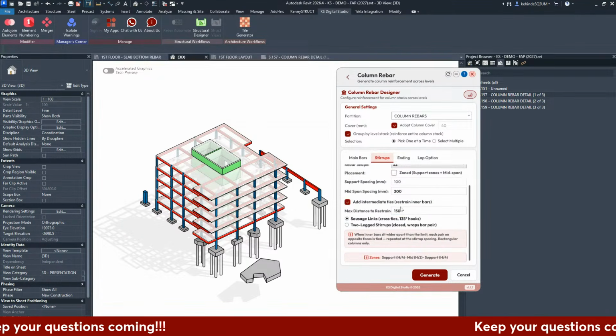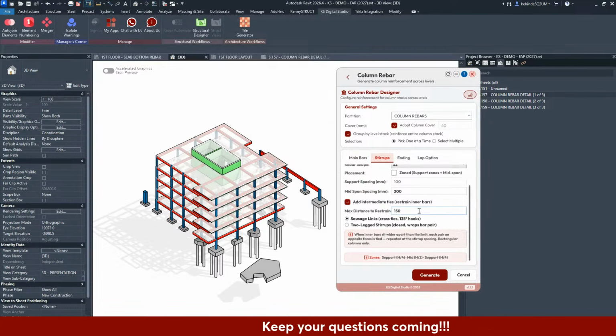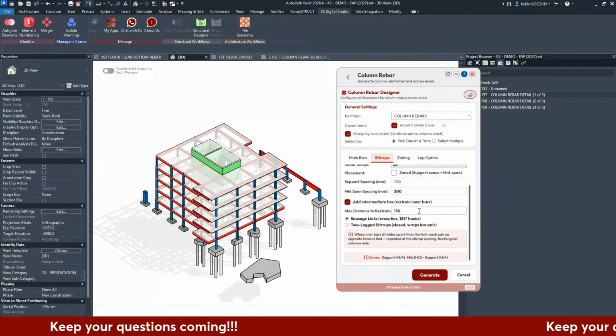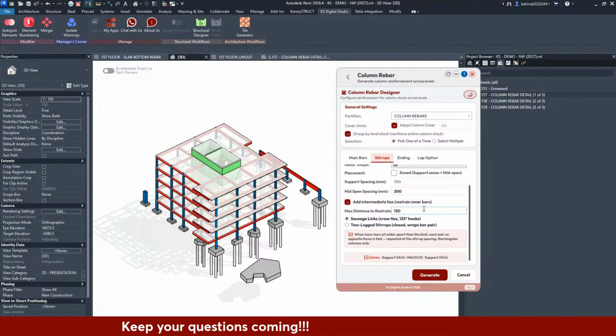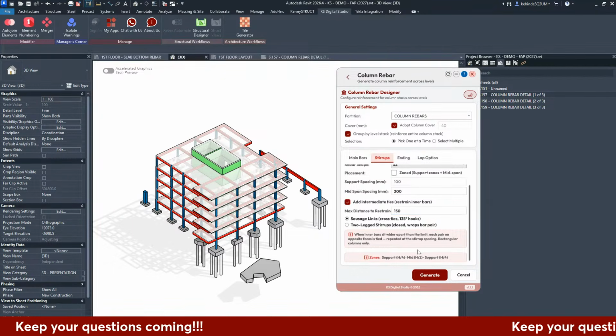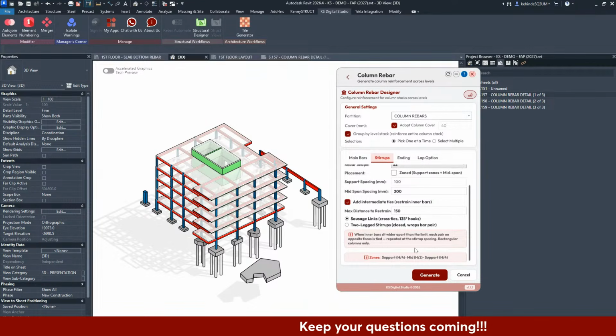We also had that intermediate type, for the situations in structural design where, in columns or compression members with longitudinal bars, a longitudinal bar should not be more than 150 mm away from a restraint bar. So we incorporated that there. I'm going to put in the code reference in the next update so you can know where it's coming from.